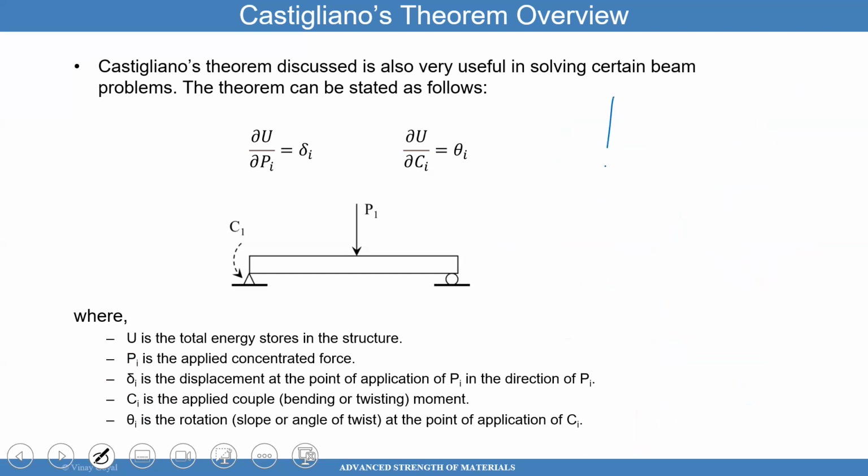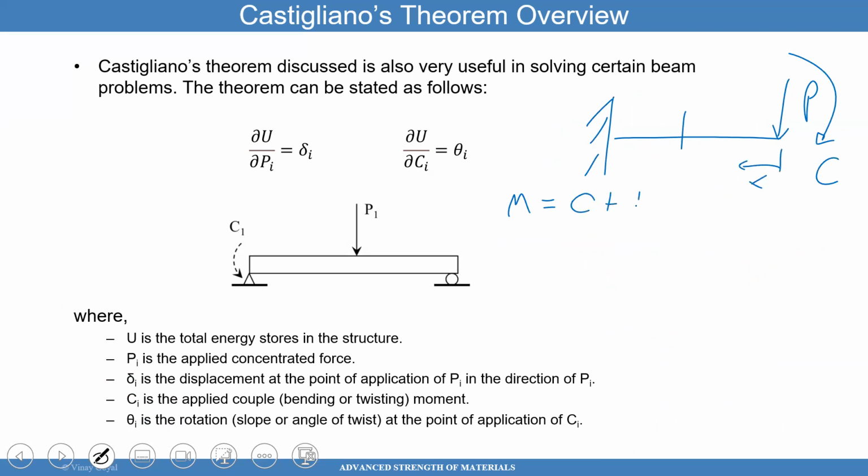What if I want to know what the slope is at that point where I apply the load P? What will you do? Put a fake moment C. Let's look at this cut there. What is the moment there? C. What else? C plus Px.